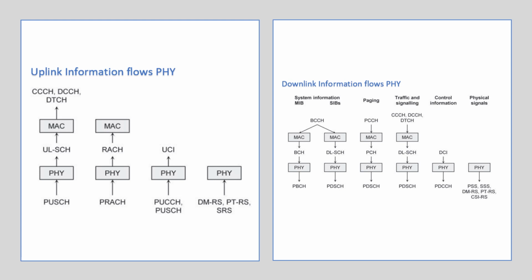Now a base station can also compose RRC paging messages if it needs to control mobiles in the state of RRC idle or RRC inactive. It delivers those messages on the paging control channel and paging channel, which maps onto the PDSCH. A base station explicitly schedules most of a mobile's uplink data transmission. However, that causes a problem because the base station does not know the exact location of a mobile in the state of RRC inactive, and does not know that a mobile is in RRC idle at all. To solve the problem, the mobile can contact the base station without any prior scheduling by using the RACH and PRACH.